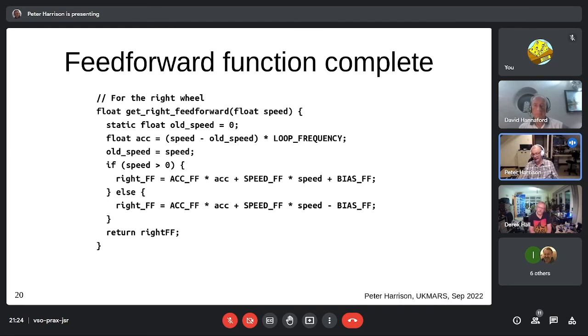And once you've got that, for that robot or any that are very, very similar, you can then get a decent estimate of the feed forward constant, and then you should be able to profile your speed more accurately than you might imagine. Certainly a hell of a lot better than just banging 5 volts out to the motors.